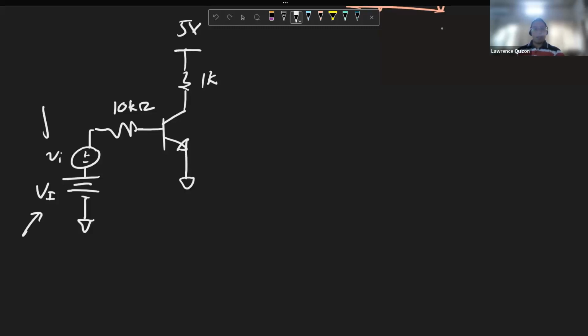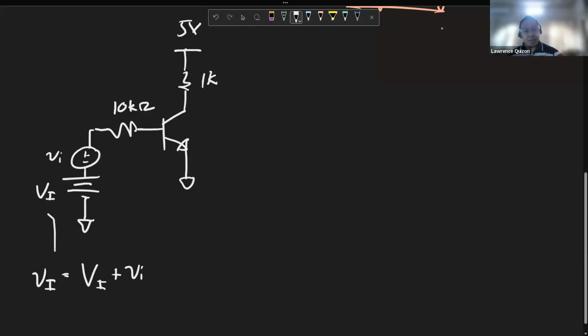It's a DC. This one is a very small value, but it's an AC value. It's an oscillating value. So that's your small signal, and your total V in would be small letter with big letter, which is equal to big letter with big letter plus small letter with small letter. Diba? So that's your total input, which leads to a V out, no?